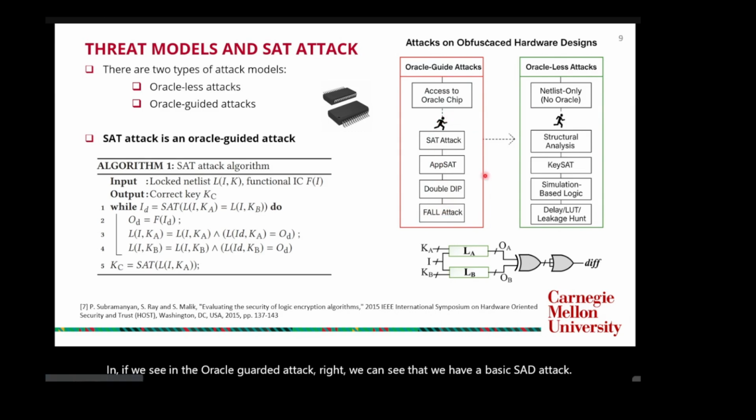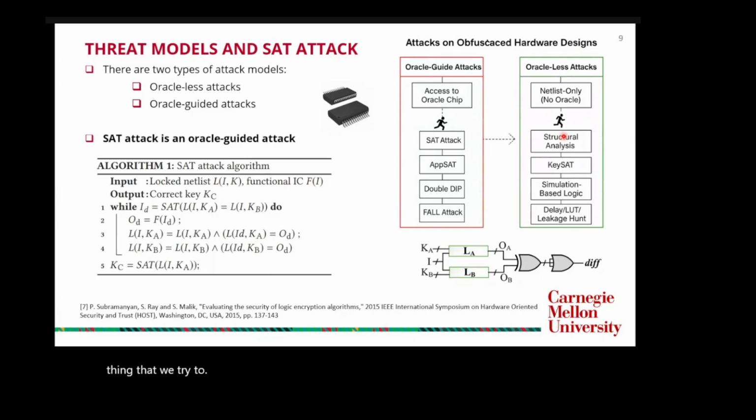So these are the attacks for logic locking, and I will mention the reference soon. On the oracle-less attack, we have structural analysis. Structural analysis is where we try to see some traces in the netlist. We have the gate connections, and we try to build the cones from input towards the output and try to divide and conquer the circuit and get some information from the netlist.